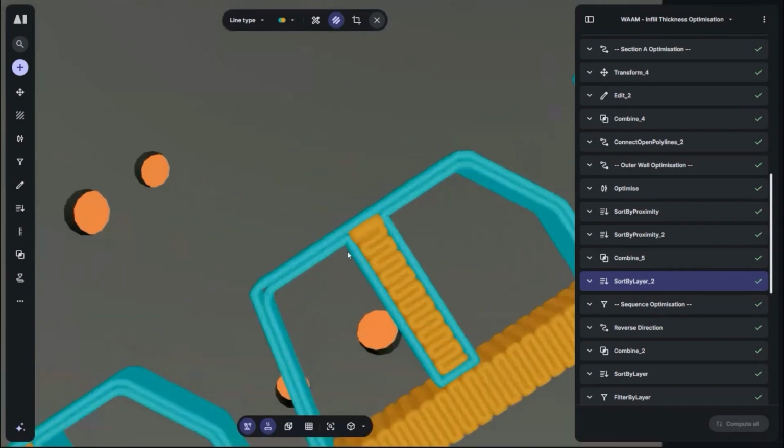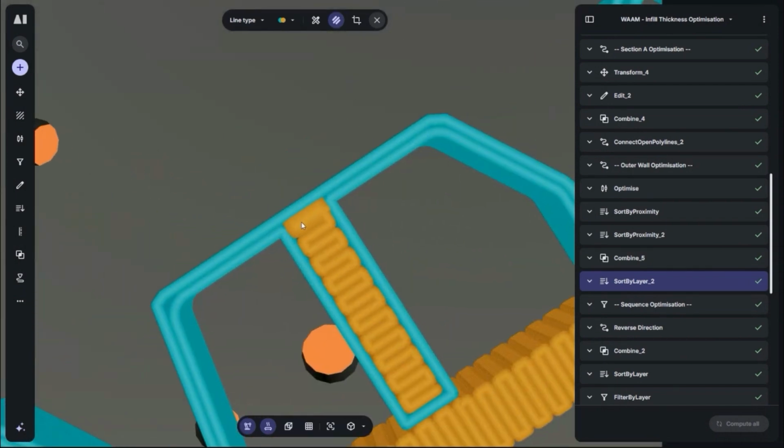You can see now that we've thickened this particular bit up, and in WireArc Additive, it's not usually the case where you change parameters dynamically based on speed and thickness, like you can with a polymer extruder very easily. Just change the RPM, sequence it, or synchronize it with the speed of the robot. Usually you're a lot more fixed to a set number of parameters in WAM.